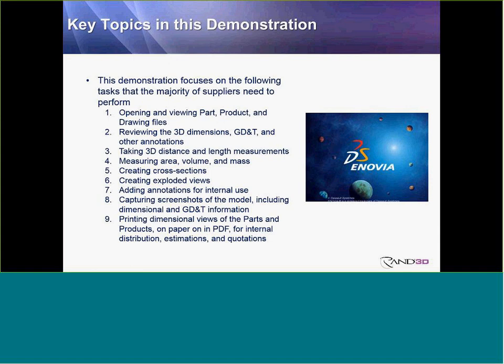So what are you going to see during the demonstration? I'm going to go over very typical tasks that the majority of suppliers need to perform: opening and viewing part, product, and drawing files, reviewing 3D dimensions, GD&T, and other annotations, taking all kinds of measurements such as distance, length, area, volume, and mass, creating cross-sections and exploded views, adding annotations for internal use, and capturing screenshots and printing.